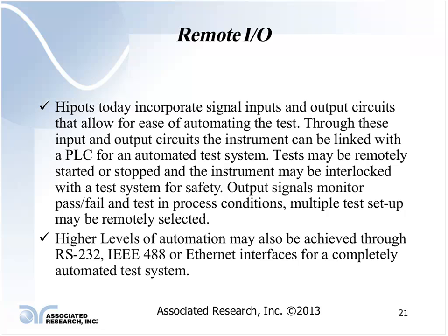If you can't come in contact with high voltage, then the operator is not going to get shocked. So if you have an enclosure for your product, or maybe even utilizing a light curtain in your testing process that makes sure that the operator cannot come in contact with the device under test, then it eliminates the shock hazard.